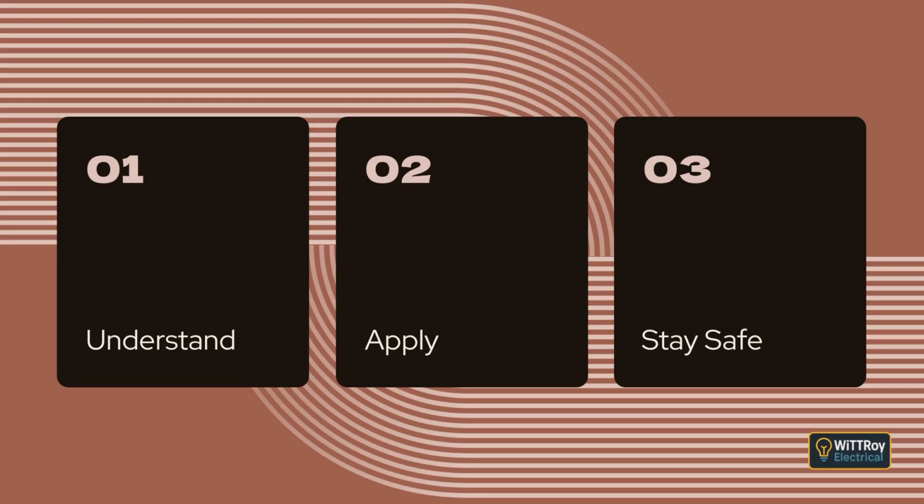Clause 3.11 Underground wiring systems. This clause explains how underground wiring must be selected, protected and installed so that it remains safe throughout its life. Clause 3.11.1 Suitability and protection. Any cable installed below ground must be suitable for the soil or environment it is placed in. It must also be protected against accidental damage, especially from digging or machinery. Where there is any chance that the cable might be struck during excavation, suitable warning systems, markings or protective measures must be used to reduce the risk.